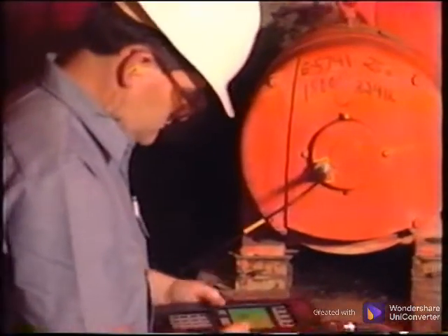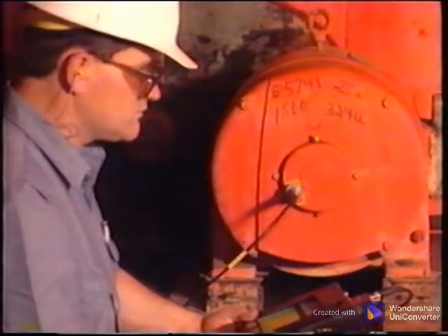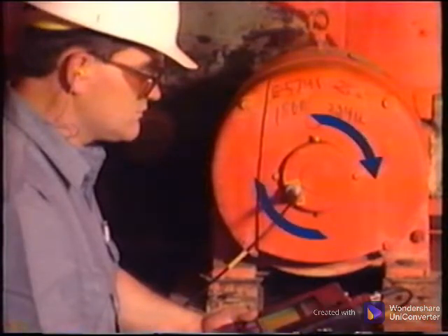The best place for an axial measurement is near the shaft center and on the bearing in the load zone. The load zone is the radial direction the most force is applied during normal operation. In horizontal machines, this is usually in a clock face position of 4 to 5 o'clock or 7 to 8 o'clock, depending on the direction of rotation.